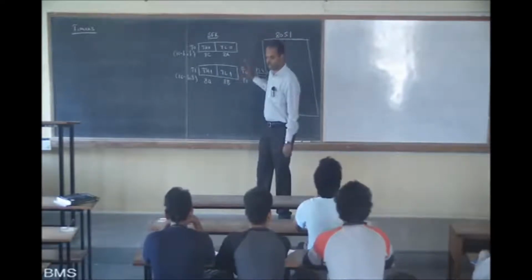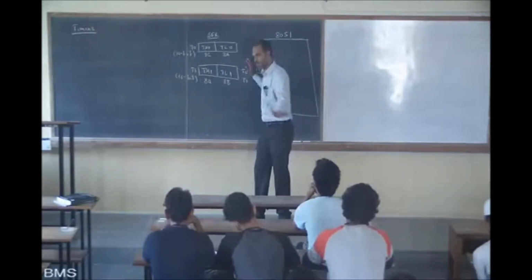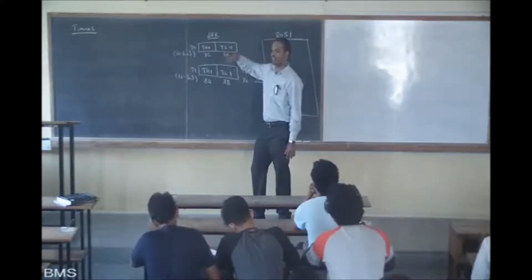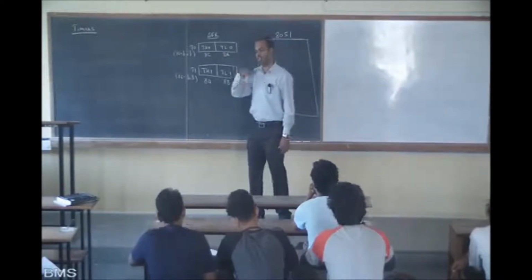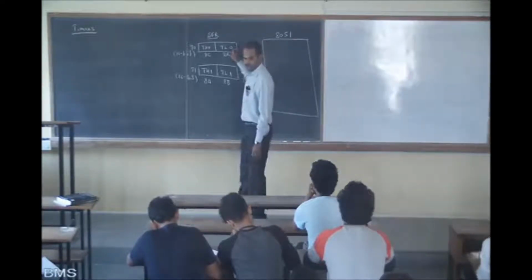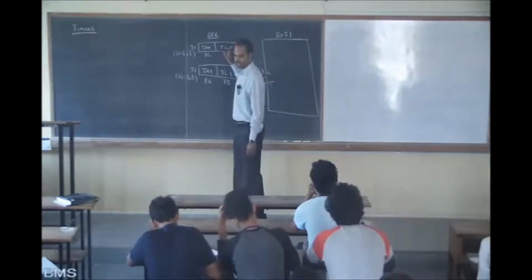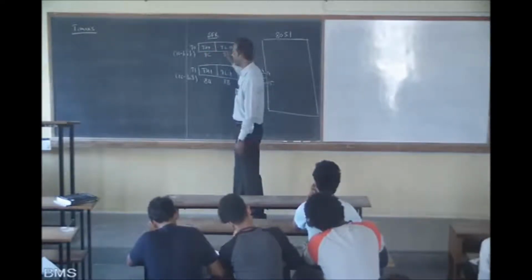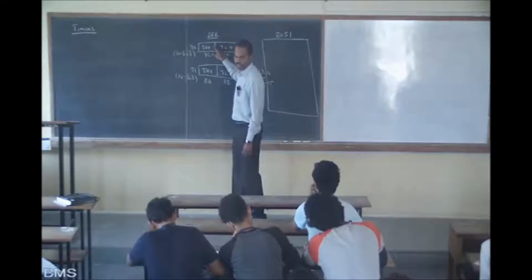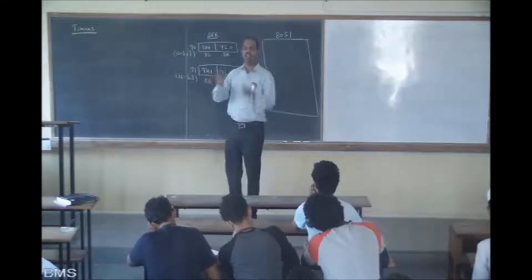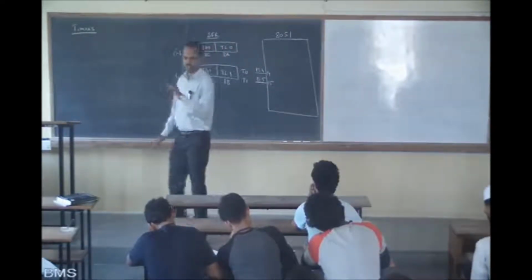Please note, the way we are discussing this is not in any single textbook. It is a combination of four textbooks, and I am just combining all these concepts, so I wish you would write it down for ease of reading. TL0 and TH0 are 8-bit registers connected in an up counter manner. If I take the output of the 8th flip-flop and connect it to the next one, it becomes a 16-bit counter. Only up counter, there is no down counter concept.